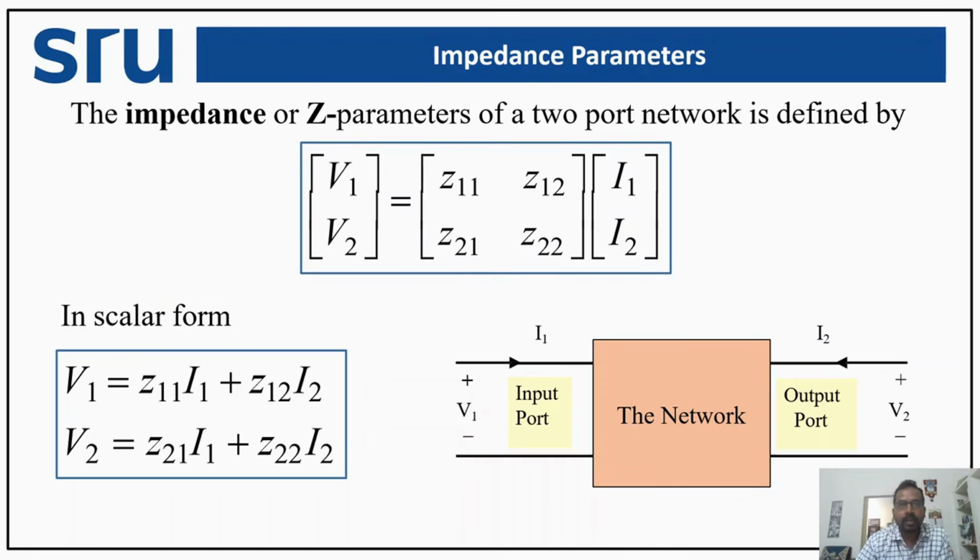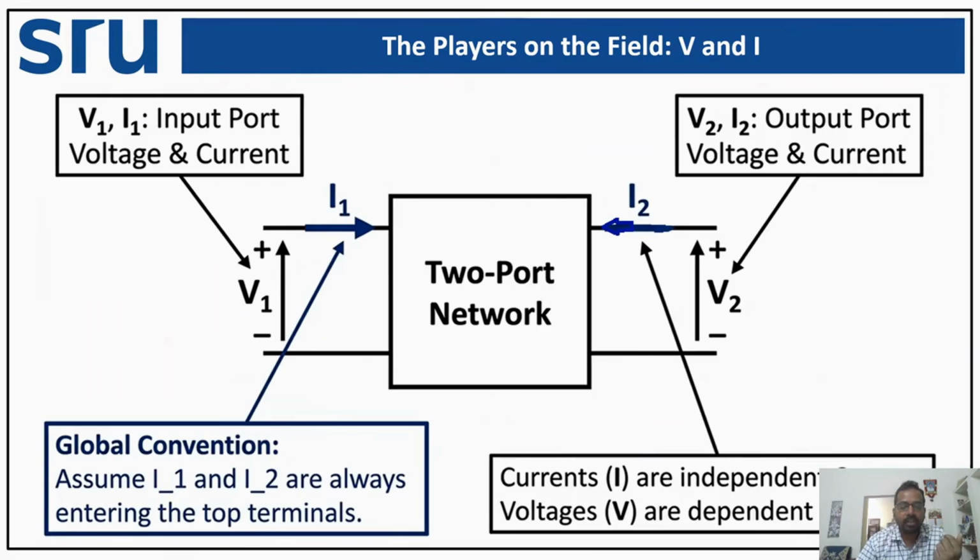Another important example is the transmission line. In power systems and communication systems, a transmission line connects the sources with the loads. So there is an input port where the power is getting transmitted and an output port where the power is getting delivered or received. These lines can be represented as two-port parameters for easy analysis. Thus, the concept of a two-port network allows engineers to simplify complex circuits into manageable models.